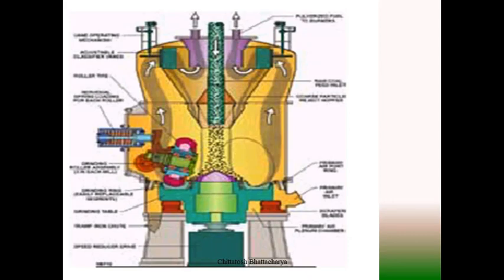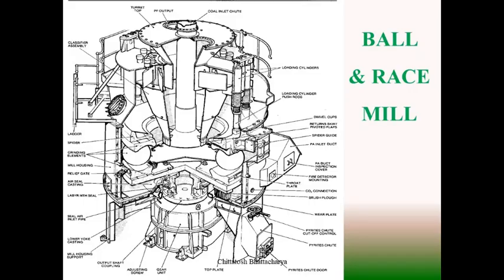The MPS mills are higher capacity bowl mills. The only difference from the bowl mill is that in the roll journal assembly, the roller journals are fitted with grinding elements which are wheel shaped instead of a tapered arrangement, and they have capacity more than the bowl mill with roll journal assembly. This kind of arrangement is more robust and has better grinding capacity.